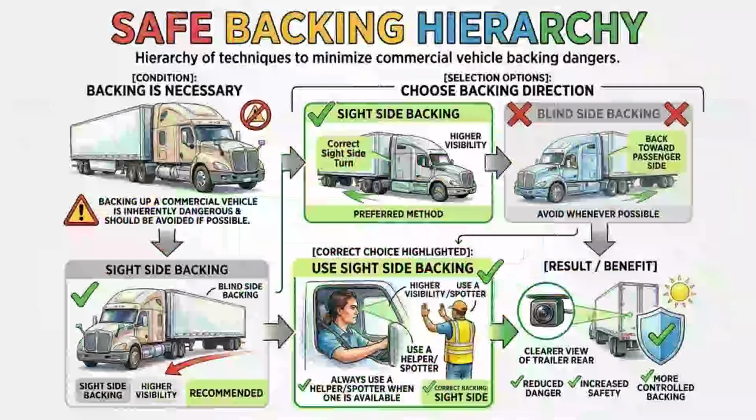Proper steering technique is simple but often overlooked by new drivers. You should hold the steering wheel firmly with both hands, typically placing them at the 3 o'clock and 9 o'clock positions. This grip gives you the best leverage and control if you hit a pothole or experience a sudden front tire blowout. Driving a commercial vehicle with only one hand is dangerous and will cause you to fail a road test instantly. The written exam might ask you about hand position to ensure you understand how to maintain control during emergencies.